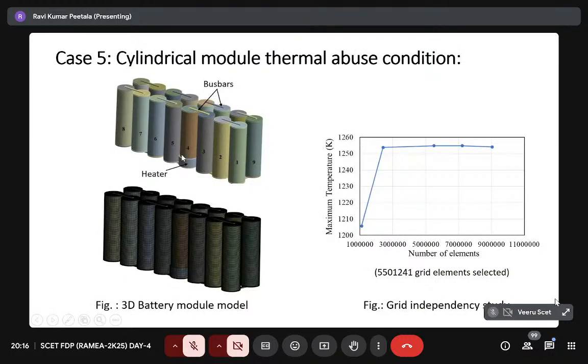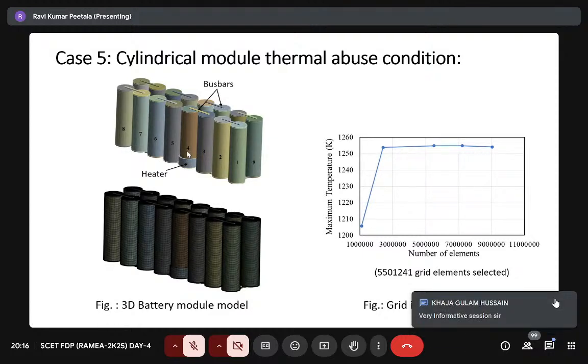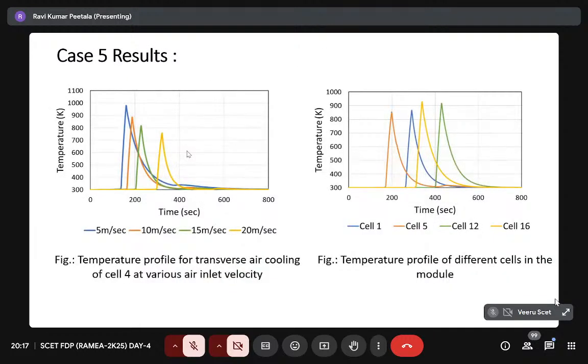So here what I did, I'm heating this surface intentionally. This is the defect battery, battery 4 is the defect battery, which means I'm giving it heat intentionally, so as to see how the temperature dissipates over the pack and what the temperature rise is. That is what I'm doing. This is that battery's cell temperature.